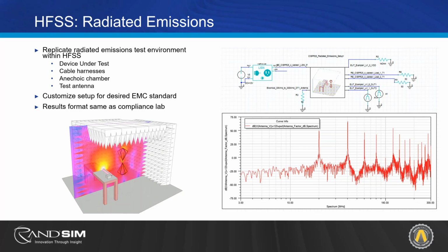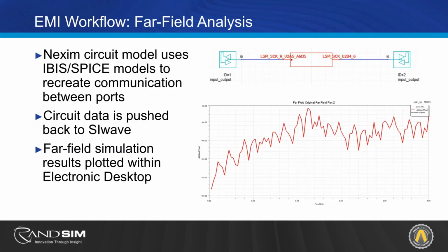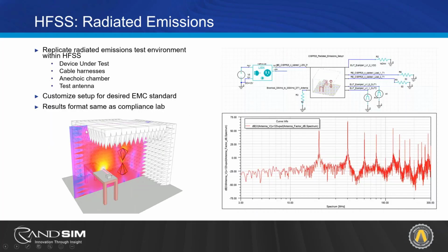The cost primarily being simulation complexity and time. So if we were to compare the simulations on the SIwave EMI tools, even the far field and near field data that I showed, this is still orders of magnitude more time and computationally exhaustive because we are calculating the full 3D wave in this scenario.